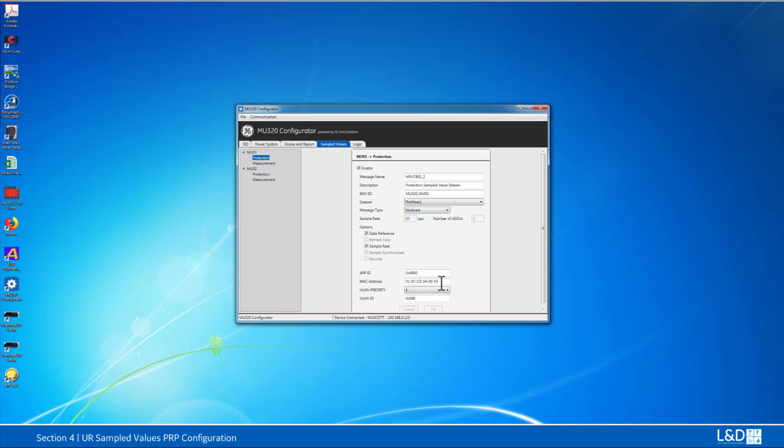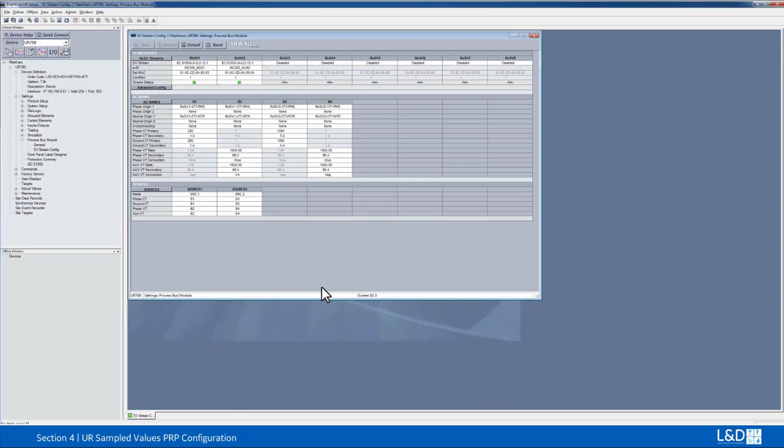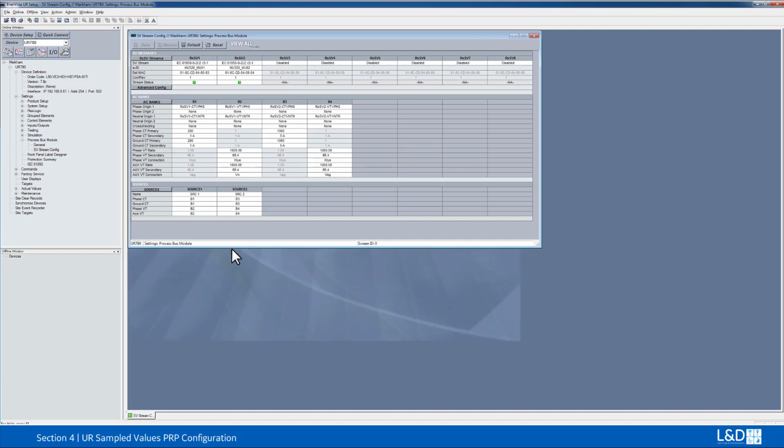The MU01 has the 03 MAC address, and the MU02 has the MAC address of the 04. And that's the information I typed into the NVista. Once we type in this configuration, we just need to save and reboot the relay, just like we did the configuration for the direct connection point to point. Other settings, like the clock setup, are the same as point to point too. I will not repeat that here.